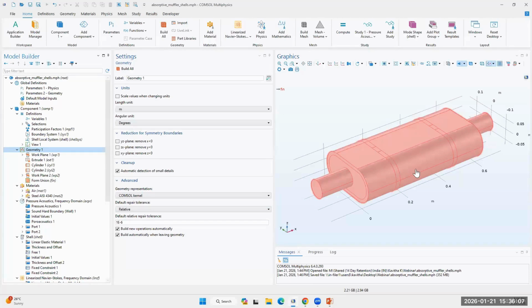So here you have a 24-liter resonator chamber with a section of centered exhaust pipe included at each end. And this model is also lined here, so you see a lining here as well, right? This is almost a 15 mm of absorbing glass wool. The exhaust fumes enter through the left pipe and exit through the right pipe.